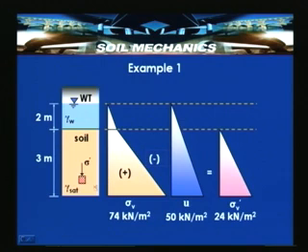So, this is the distribution of the total stress with the depth. This is because of the unit weight of the water. The slope of this particular line is different because of the saturated soil unit weight. So, this is the pore water pressure, and this is the effective stress, which is nothing but total stress minus pore water pressure. It gives us effective stress is 0 at this point, and effective stress at this point is sigma V dash equal to 24 kilonewton per meter square.